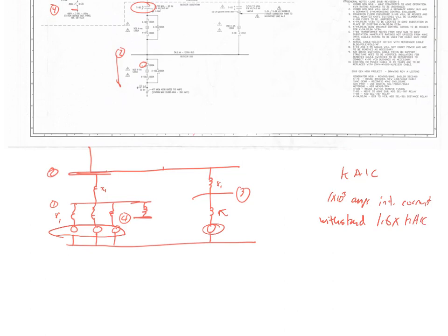And a lot of times when you do breaker coordination, and I don't know if anybody here has done that, you can actually look at what fault current levels are and see, can the breaker actually handle it? There was a question from Dan about why they put these reactors, these inductors, in series with these circuits or systems, and why not resistors? Well, resistors do consume real energy, so those are consuming watts. That's energy into the system. If you put inductors in there, they don't consume any real energy, but they can reduce the fault current levels.